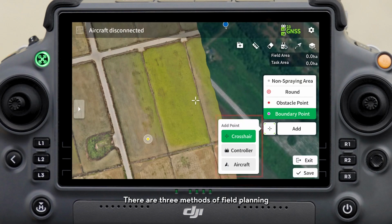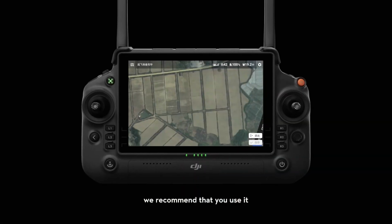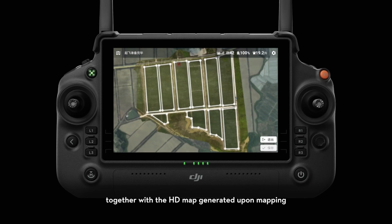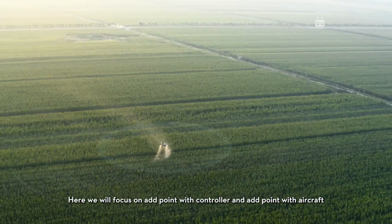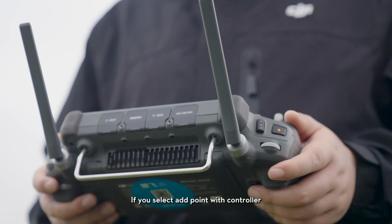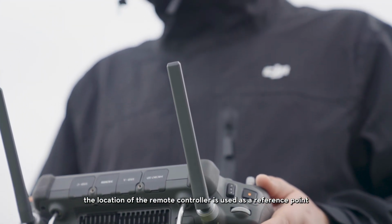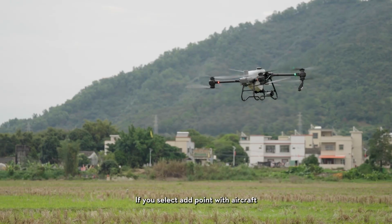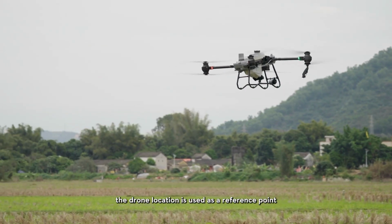There are 3 methods of field planning: crosshair on the map, add point with controller, and add point with aircraft. If you select crosshair, we recommend that you use it together with the HD map generated upon mapping. Here, we will focus on add point with controller and add point with aircraft. If you select add point with controller, the location of the remote controller is used as a reference point. If you select add point with aircraft, the drone location is used as a reference point.